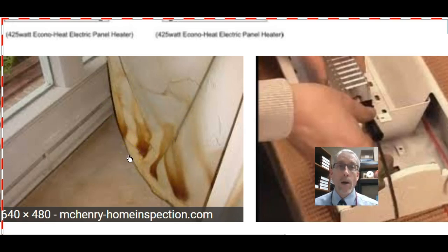That's one of the more common ways for fires to start, is for some piece of cloth that even could be like bedding, like a bedspread or sheet, that gets thrown over top of a space heater. And that's a surefire way to, no pun intended there, to start a fire. So always keep any kind of flammable material away from electric radiant heat.